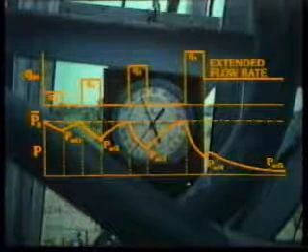In practice, the well is flowed at 4 different rates, with the duration of each flow period being equal and usually relatively short. Thus, for example, an operator may allow each of the 4 flow rates to last for a period of 1 hour. The well is shut in after each flow period to allow the pressure to stabilize, as shown here. After the 4th flow rate is completed, the well is produced at a selected constant rate until stabilization of pressure during flow takes place. The last rate may not be as high as that selected for the 4th flow rate of the test.